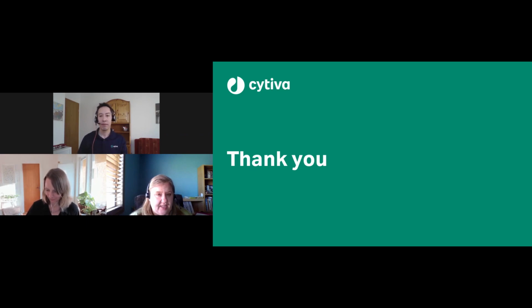Okay, and I think the last question then is for you, Alex. Are there any available compatibility data included for leachables and extractables with highly concentrated buffers in single-use bags? It is dependent on what would be defined as a highly concentrated buffer, and the film used, of course, within that single-use bag. So sometimes it's dependent as to which specific buffer, which specific bag, if it's established on the market.